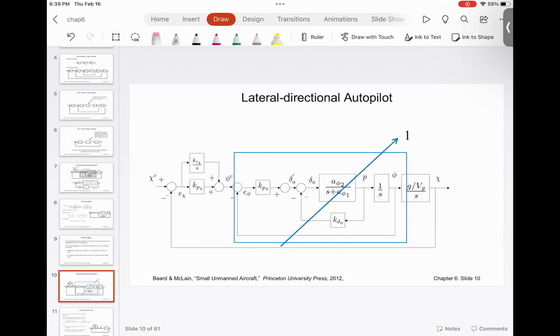Now, what's going to happen is all the transfer functions that you have in the innermost loop, here is what we are going to do. We are going to adjust the KD, this guy, and we are going to adjust the KP, that guy, so that this internal loop becomes one. Everyone understood this? That's exactly what we are going to do, and that is internal loop closure. And then we are going to go outside and close the outside loop.